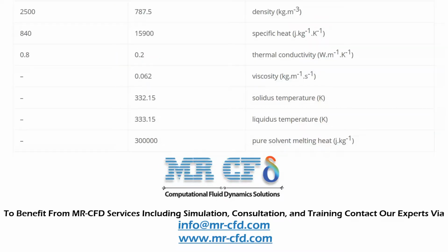For the present modeling, a glass coating around the chamber containing phase change material with a constant temperature of 338.15 degrees Kelvin has been used, which is responsible for transferring heat to the phase change material. The PCM in the initial state of simulation is at 332.15 degrees Kelvin.